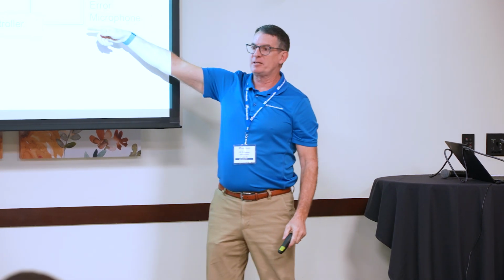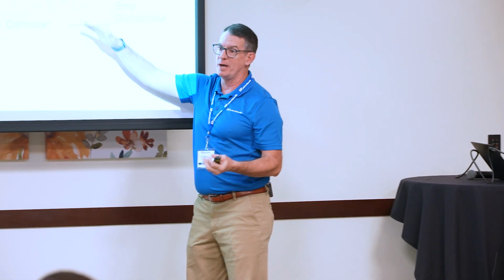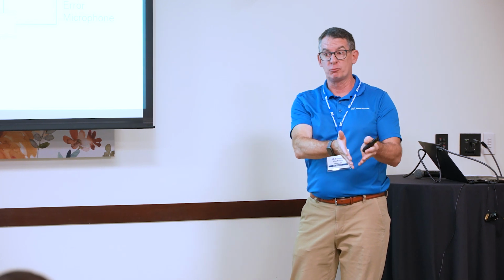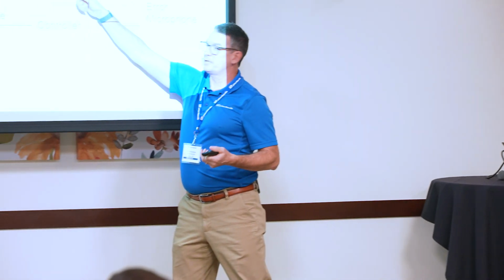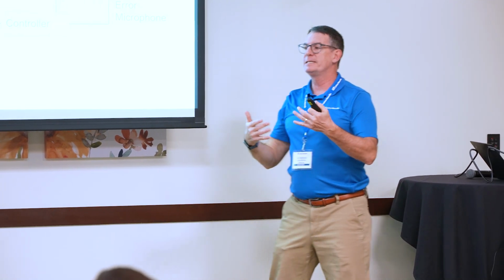To me, active noise control and passive noise control like insulation work really well together, because insulation does an awesome job at controlling noise in that mid to high frequency range, but the really low frequency rumbles are tough because those sound waves are so long. Active does awesome at the low frequency. So to me, this doesn't replace insulation. It is an excellent complement to insulation, especially if there's a big need for a lot of noise control across a broad range.